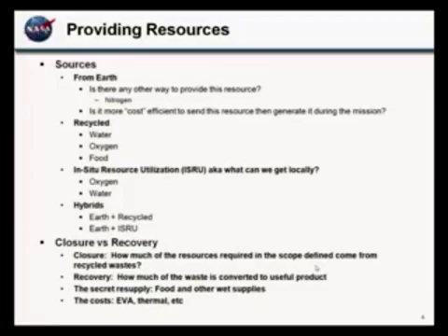All of those things need to be considered. Recycling. When we start to think about how we can produce a resource, there are a lot of different sources of waste which may or may not all be equally valuable. Condensate water is essentially already distilled because it's been taken from humidity and condensed back out. So that's a very clean water source. So like Bob said, the Russians use that to power their oxygen generator because it's a relatively easy resource to recycle.